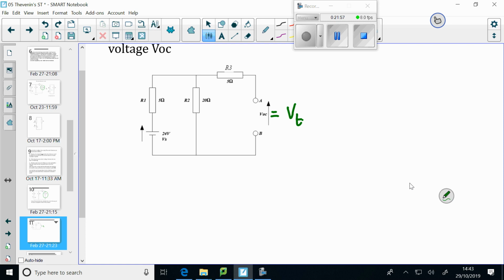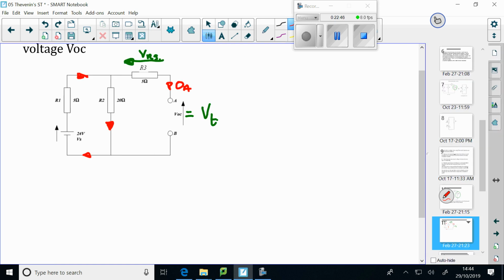First of all, I'll ask you a question. How many volts have been dropped under these conditions across R3? An even earlier question than that, which way is current flowing in this wire? What about here? How much current flows in this one? That current, under these conditions, is 0 amps. So, how much voltage is being dropped across R3?